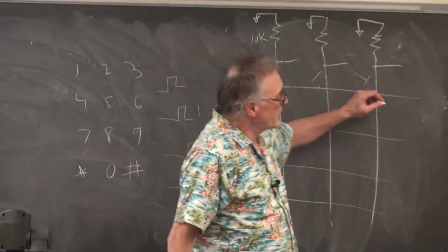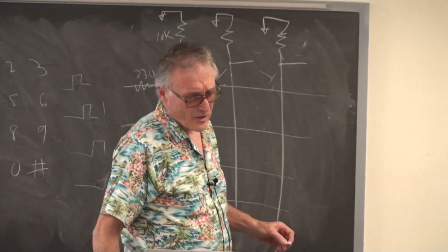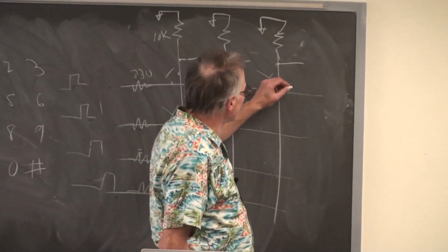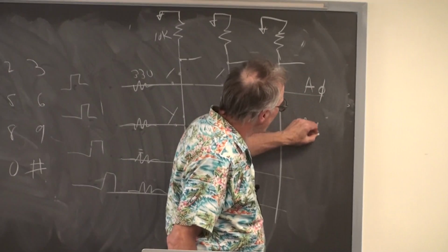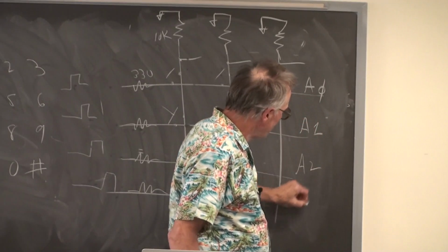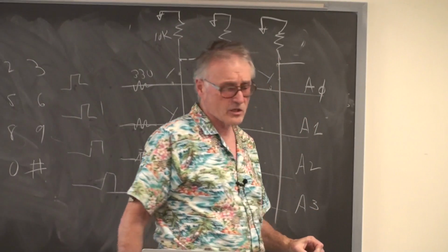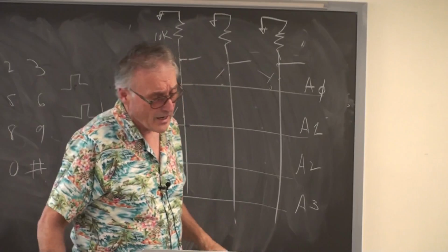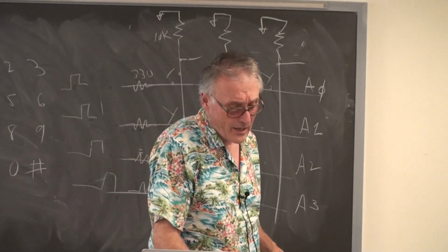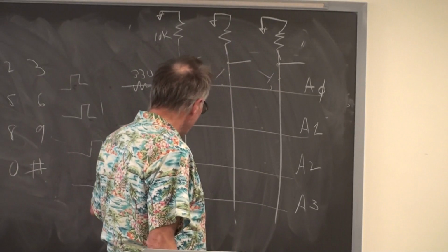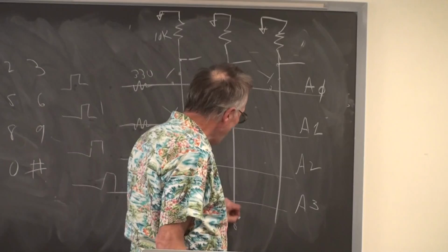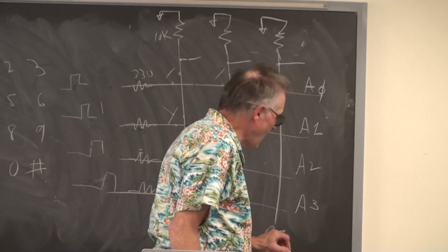So what I did was, and I want to make sure that what I ran on the board agrees with the code, I mapped these to A0, A1, A2, and A3 digital outs. And I mapped the 3 bits here to B7, B8, and B9.